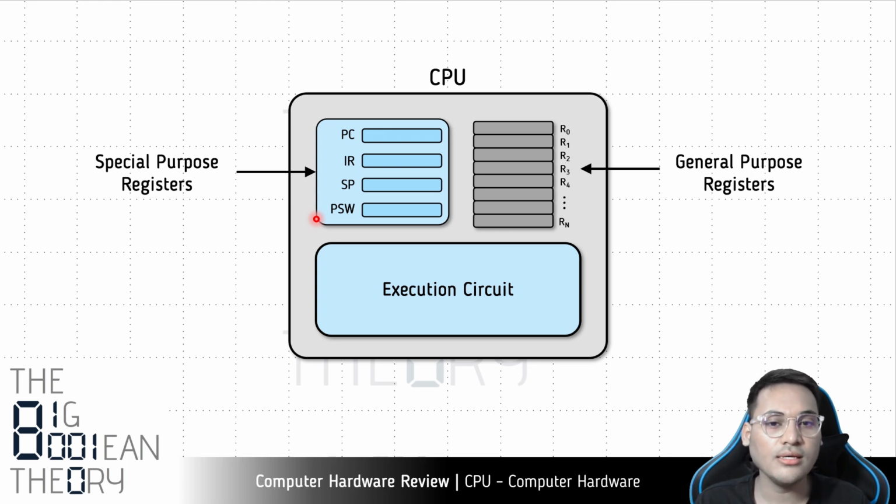So it's a place where you store different pieces of information as a collection of flags, and it can be used by the CPU to check if some condition has occurred, and depending on that, some special action may have to be taken. So this was about the program status word. These are some of the examples of special purpose registers that we just saw.